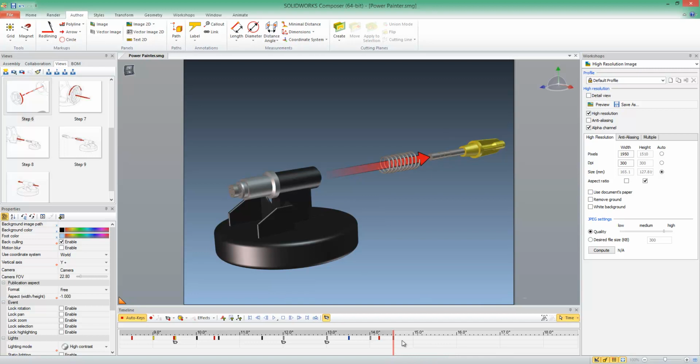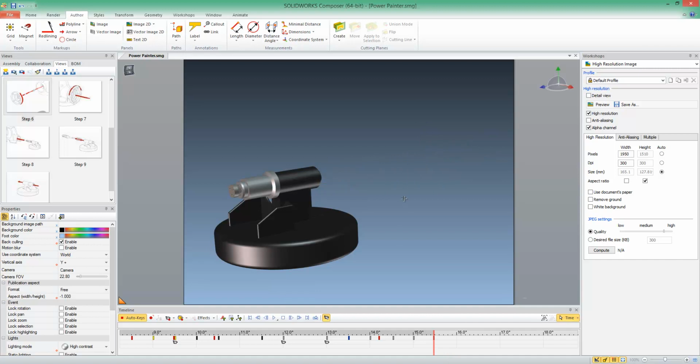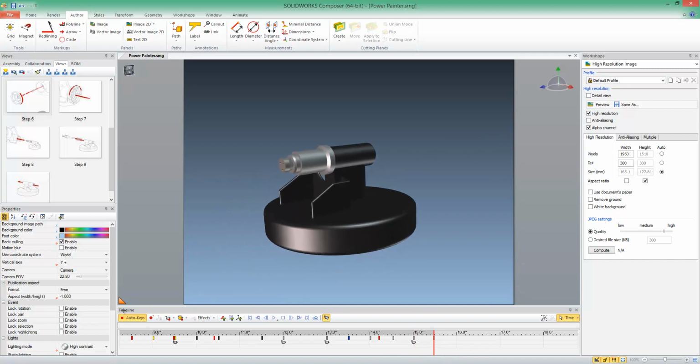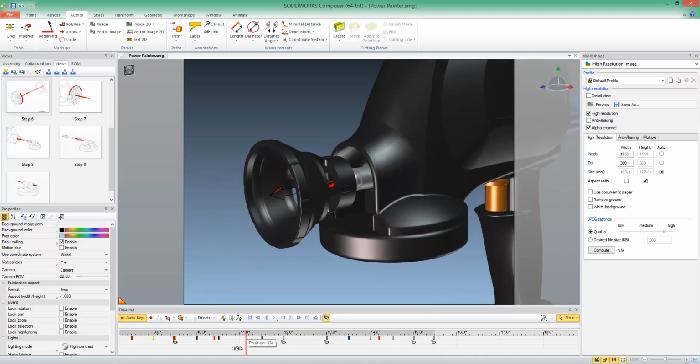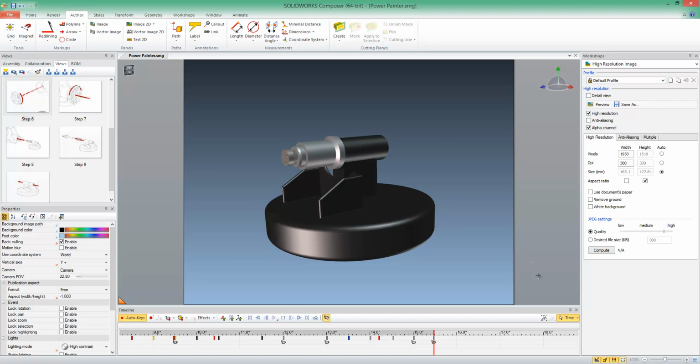Then what I want to do is have half a second gap. I'm going to record the properties of those components at 15 seconds, and then at 15.5 seconds I'm going to fade them out like so. The section's looking pretty decent now. The last thing I want to do is just change my orientation to the model. So at 15 seconds I want to be zoomed out where I am, so I'll just create a camera key there, and then at 15.5 seconds we'll just zoom in and record that position. So if we just play the last bit of that animation, I'd say that's looking pretty good.